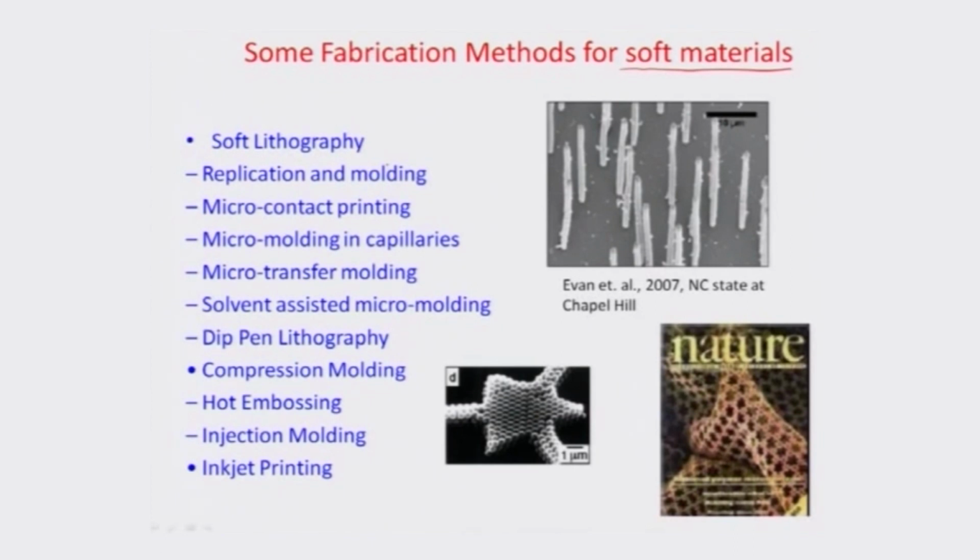The domain of processes used mostly for the fabrication of these soft materials is also known as soft lithography, just because you are using soft polymers. You use one step of lithography, and the mold that you eventually create can be used many times to have the soft material molded again and again across that mold. So, you have one step lithography followed by soft material driven micro molding, which results in features and structures at the micro scale, and you can prototype very rapidly as well.